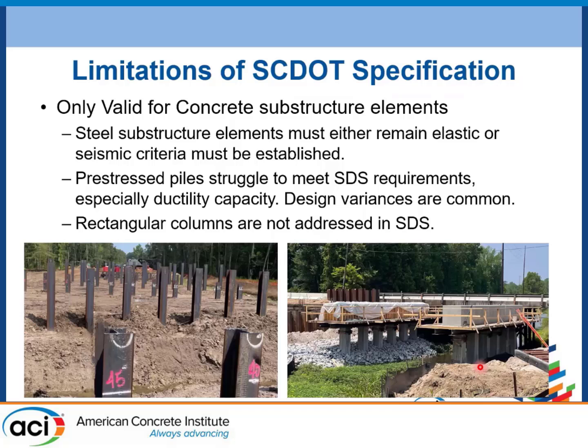A few limitations from South Carolina's perspective. First off, this SDS, the South Carolina Seismic Design Specification, is only valid for concrete substructure elements. I know here at the ACI conference, everybody's cheering that. You know, concrete is our primary interest here, right? But there are steel substructure elements, and what you see on the lower left is actually a place where we've used steel piles as our primary substructure element. We had to work with the DOT to discuss meeting seismic requirements for that bridge.